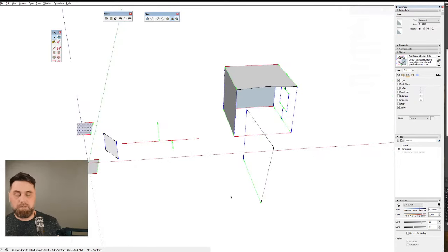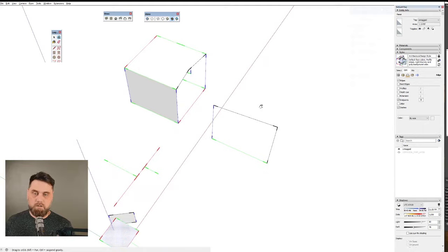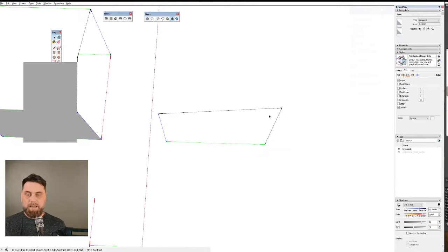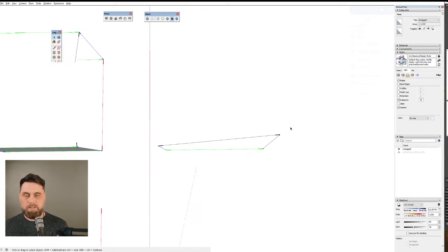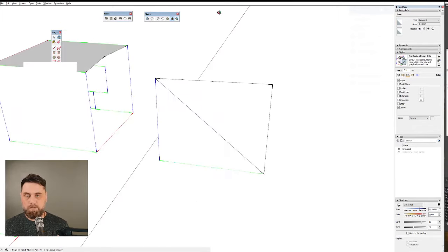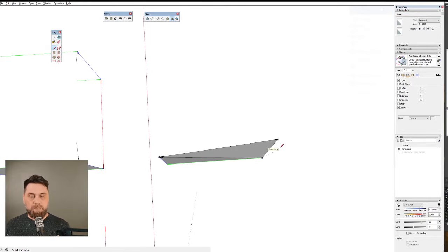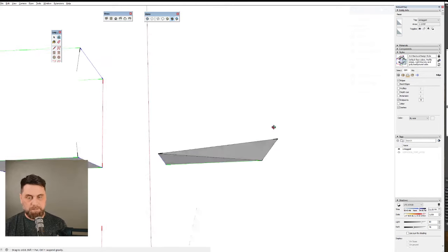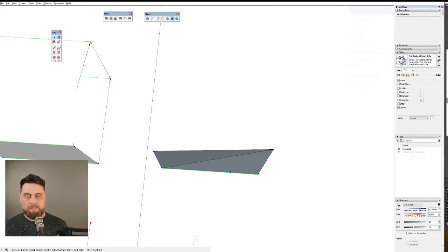So, all right. The way that you cheat is to draw a diagonal edge. Okay. So imagine if this was framing, right? If these were stick frame 2x4s and this one was pushed back, well, you couldn't draw a diagonal line this way. I guess you could. Yeah. Because now those three are going to create a triangle, which is planar. All right. Or we could go the opposite direction, and now it's going to be coplanar, just in a different orientation.